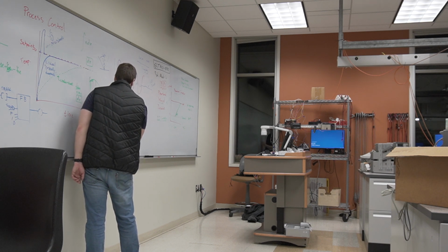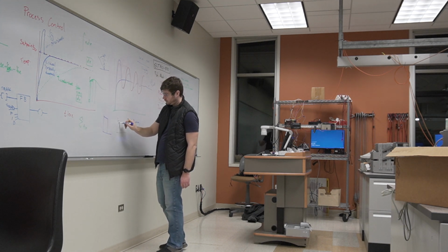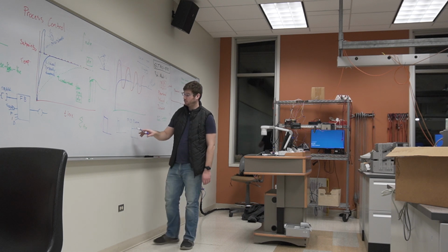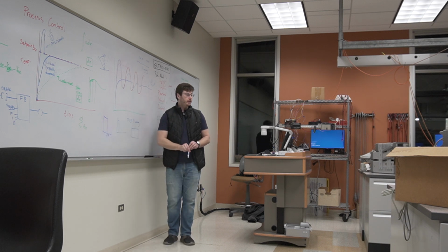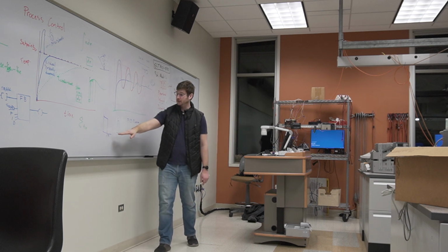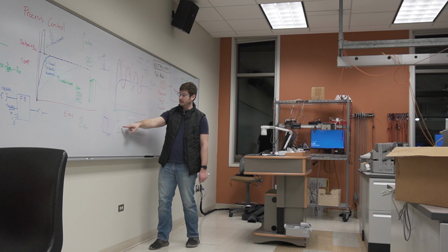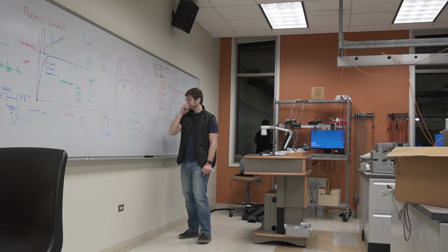This is what a 50% duty cycle looks like. This is what a 25% duty cycle looks like. This is what a 100% duty cycle looks like. You can imagine that this waveform is on 50% of the time and off the other 50% of the time. And then this repeats itself like 1,000 times a second. So every 1,000th of a second, it's on for half of a 1,000th and then off for the second half of the 1,000th. Over here, it's on 25% of the time and off 75% of the time. So on and so forth.